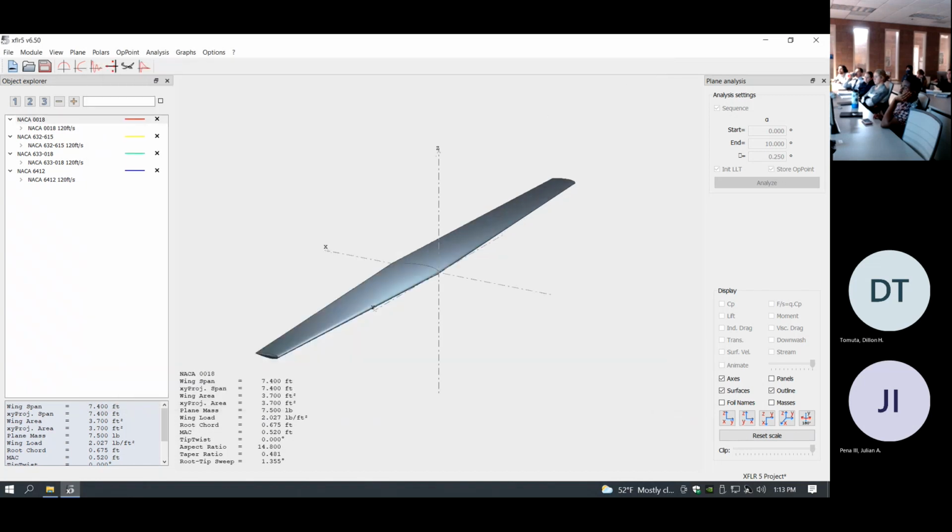Yes, Zoe. For the maximum thickness, is it supposed to be 25%? For a conventional airfoil, yes. It's supposed to be around 25% chord length, but the airfoil I showed was non-conventional, which means the maximum thickness is not at quarter chord. It's moved further behind the chord length. That one was at 34% chord. Okay, yeah. So 5 digits comes with quarter chord as the maximum thickness. That's conventional design, and those were both 4-digit series airfoils anyways.